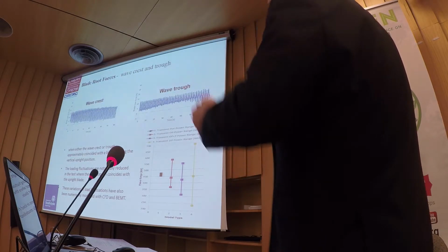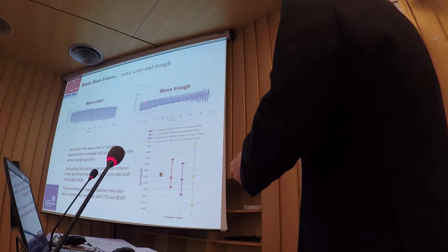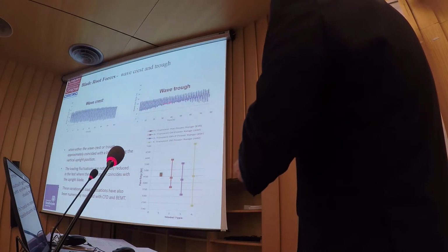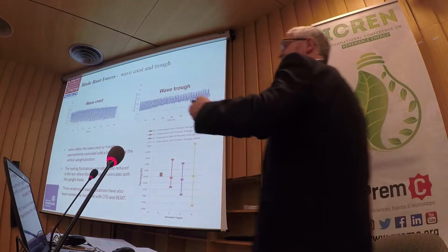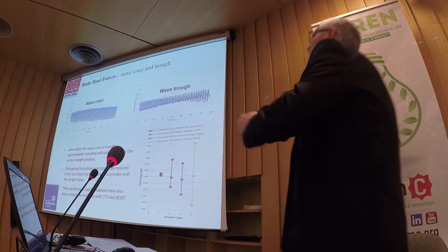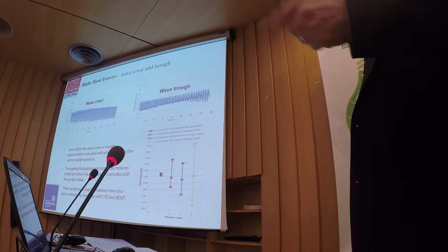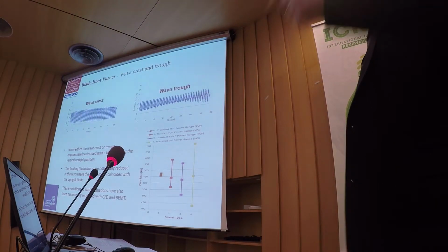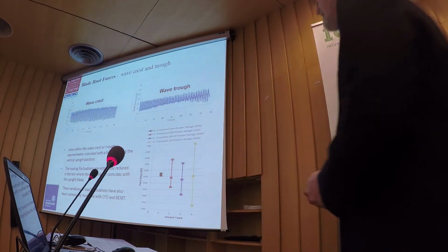If the blade hits at a trough when it's vertically upright, you get a much tighter loading variation. So this could come down to the fact that if you know what your wavelength is, you could arguably set a control mechanism that changes the rotational speed so you actually miss if the wave is suitably extreme.